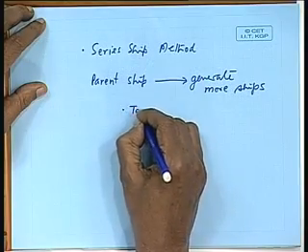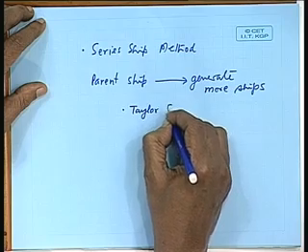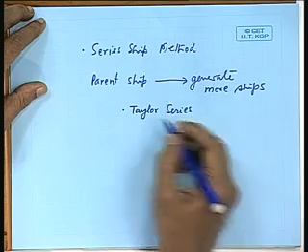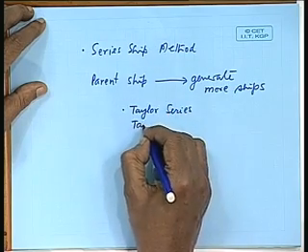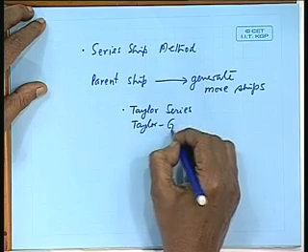So, if I generate a number of ships like this and test them in a tank, what I get is a matrix of ships for which all resistance data is available. And if I can present it properly, then for any intermediate dimension, I will be able to tell what will be the resistance. This was the thought way back in 1940s and 50s. So, we had a number of series starting with the Taylor series and later modified to what is called Taylor-Gertler series.